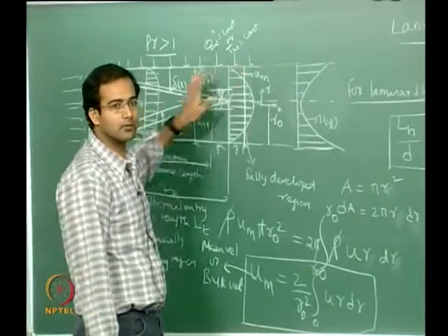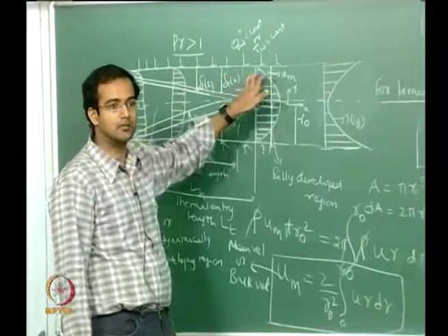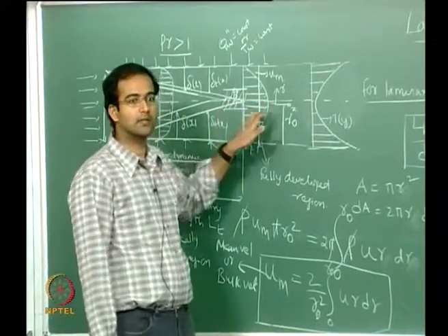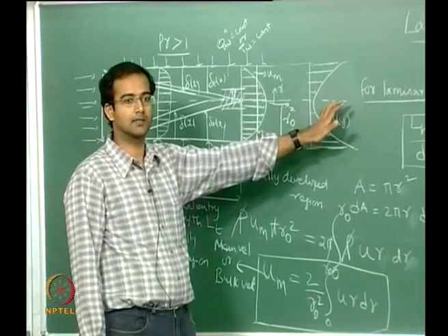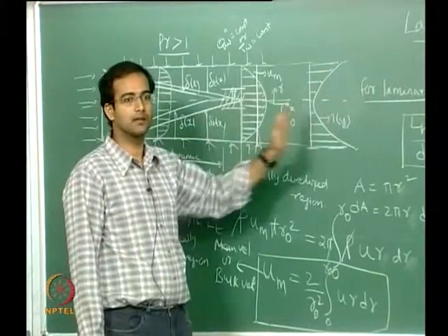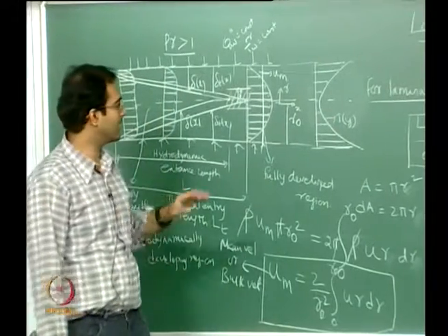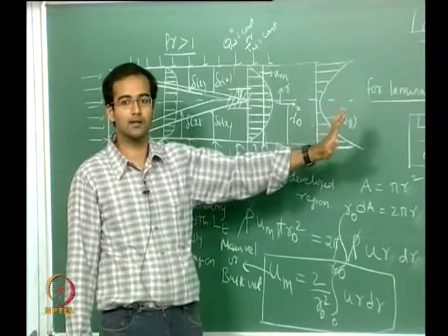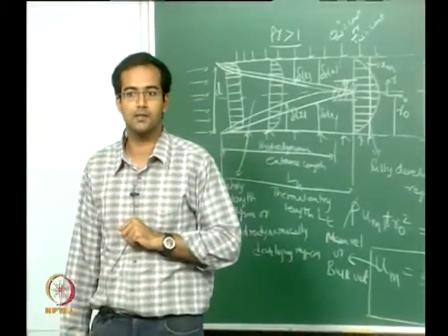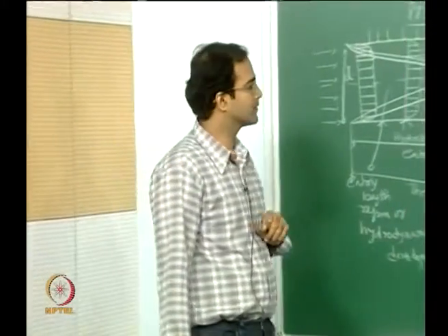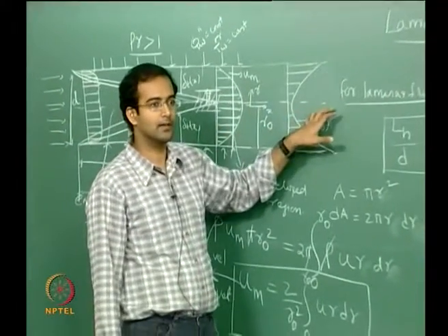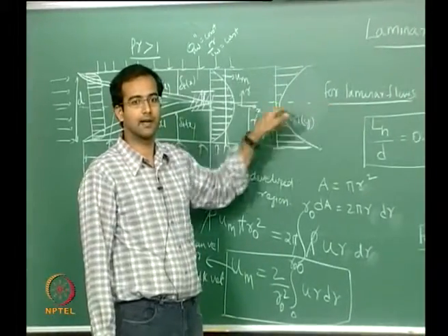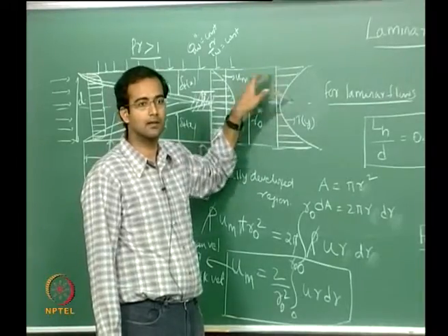So therefore, due to conduction, the wall temperature has to keep increasing downstream, and consequently the fluid also keeps getting heat continuously. So the fluid temperature also has to vary along the x. So therefore, unlike the velocity profile, which shows a constant behavior, the temperature will never be a constant value, correct? So you will find the temperature of the fluid anywhere that you plot will keep on changing with respect to x at any y location, or even at the wall, that also keeps changing.